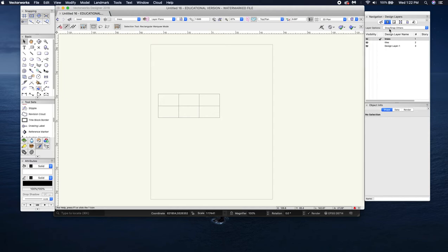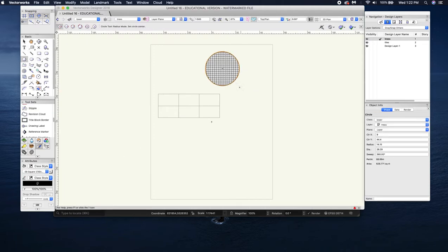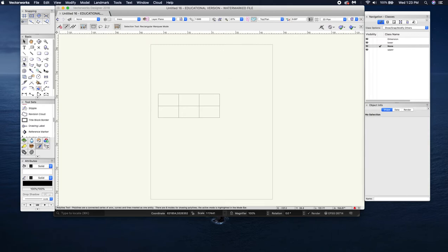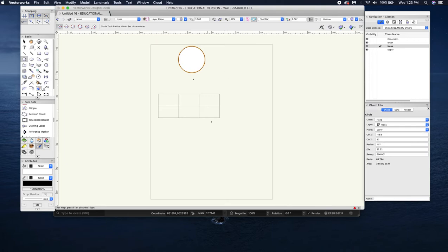And the layer options give you different ways of viewing the other layers. So for instance, oh, there is another thing that I forgot to remind you guys. Now, as you can see, I just wanted to draw a circle, but it took on the class that I selected last. So in order to prevent that from happening, you go into your classes and then click on none. Make sure it's selected. So now if I make another circle, it takes on none of the attributes from that class.